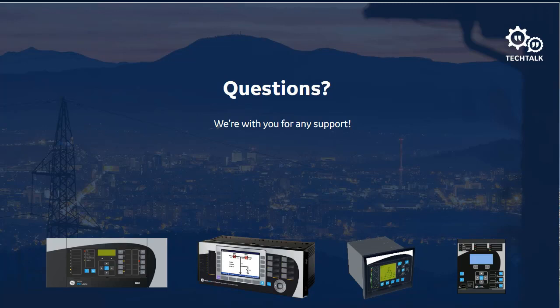So for the most part, if we use the interconnection and the fault type for currents, we can make some intelligent statements. If we don't know the fault type and we're just given the positive sequence quantity, we cannot make any intelligent statements about the negative or 0 sequence. So I guess the shorter answer is, it depends on what other information we know.